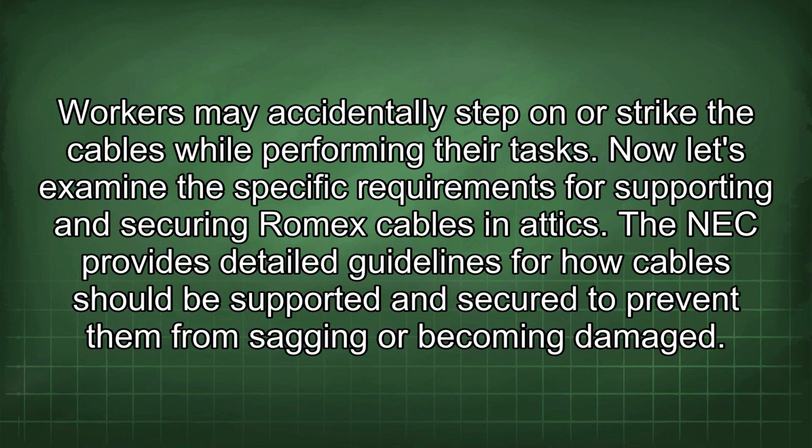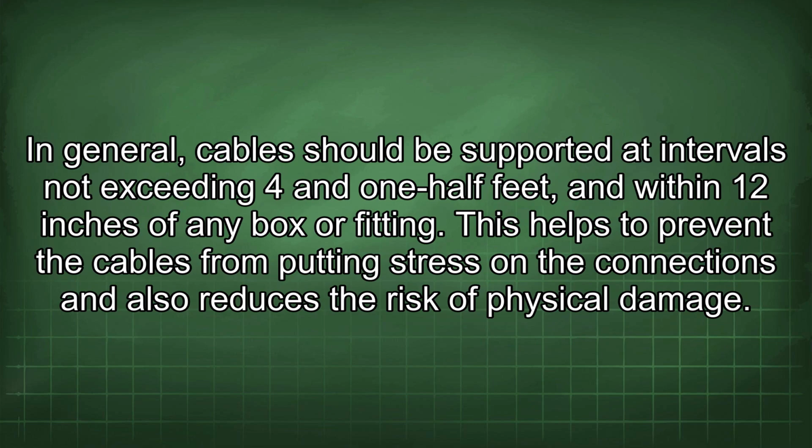Now let's examine the specific requirements for supporting and securing Romex cables in attics. The NEC provides detailed guidelines for how cables should be supported and secured to prevent them from sagging or becoming damaged. In general, cables should be supported at intervals not exceeding 4½ feet and within 12 inches of any box or fitting.